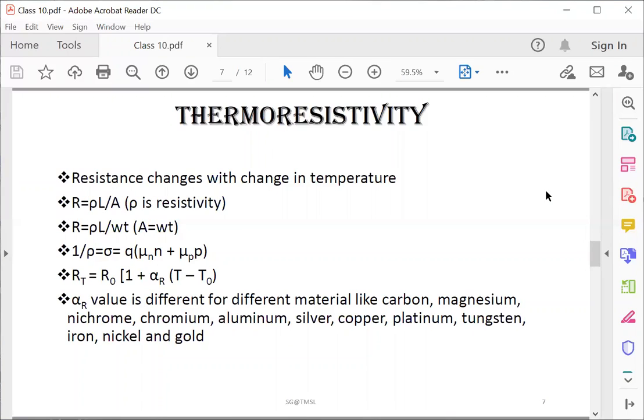For example, in the flow sensor, the temperature coefficient of resistance property is utilized, and there we use nickel as the sensing material, because of its very high temperature coefficient of resistance value. With nickel as the sensing material, for the contact you can use chromium gold. It does not matter, but nickel is a good choice for a sensor where you want to utilize the property of thermoresistivity.